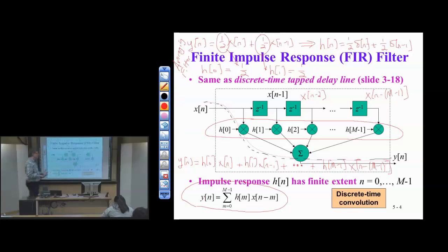But for a first order difference, the input-output relationship is right. So for the negative 1. So for the first order difference, it would be 1 and minus 1. For the averaging filter, unnormalized, 1 and 1. For the averaging filter, 1 and 1, and 1 and minus 1 for the first order difference. So it's the only difference? That's right.